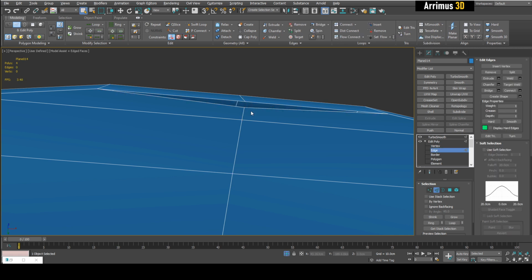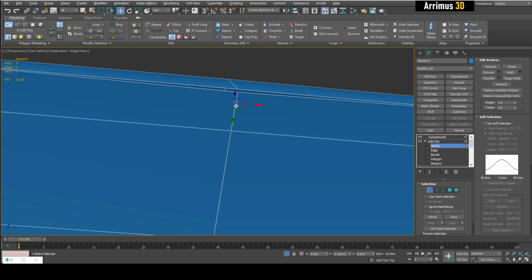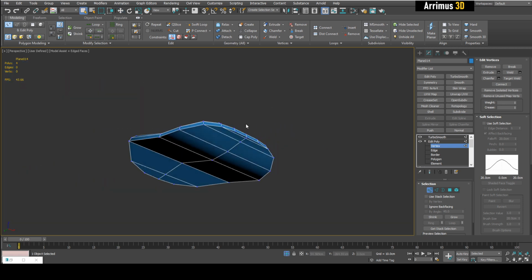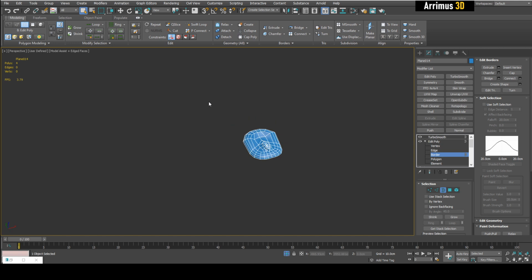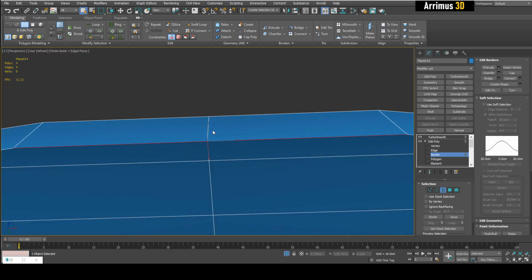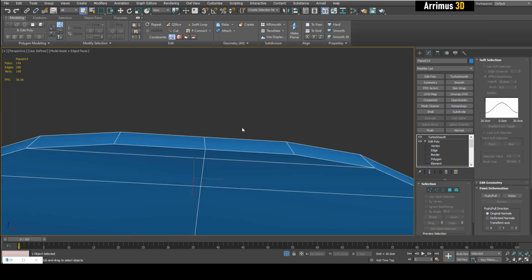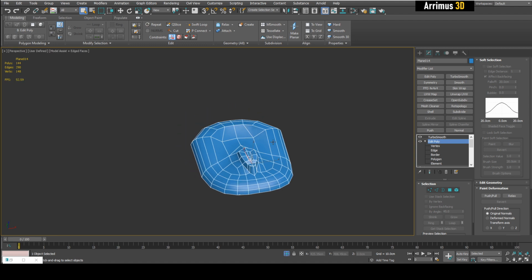and then delete this. All right, sometimes it's hard to tell because if this vertex is, let's say right here, your mesh looks airtight, looks like a volume, but if you go into border, make a selection, notice something is selected, you press Z to zoom in on that, it's going to let you know, okay, this is not welded. You need to actually weld this. There we go. So this is what I would do if I actually want to have a volume here.